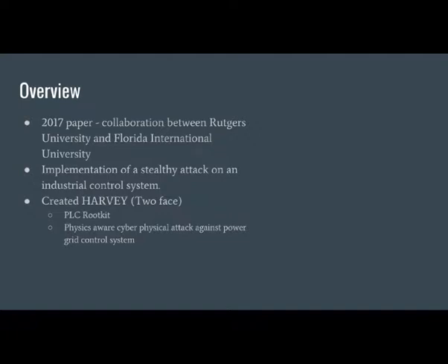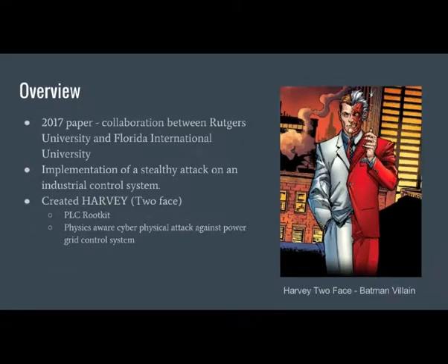Basically the question they were trying to answer is whether you're able to implement a stealthy attack on PLC systems whereby you're not going after the HMI, or the human-machine interface, and we'll explain that as we go on. They essentially created HARVEY, which is a reference to Harvey Two-Face, a villain in the Batman cinematic universe. The analogy applies really well because it's the idea of the operator seeing the benign, non-harmful side of Harvey, whereas underneath it's the deformed attack, or the other side of Harvey. They implemented this on a power grid control system, as we will see later on.